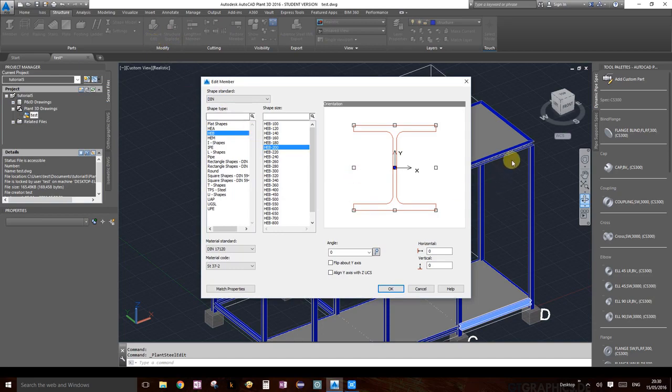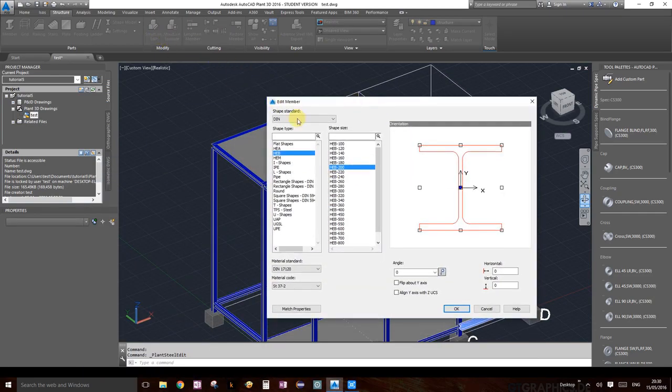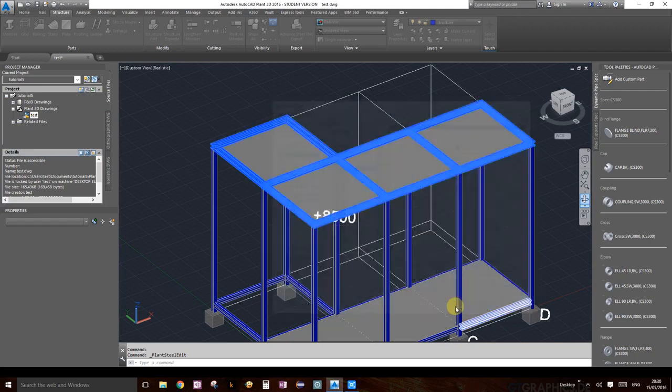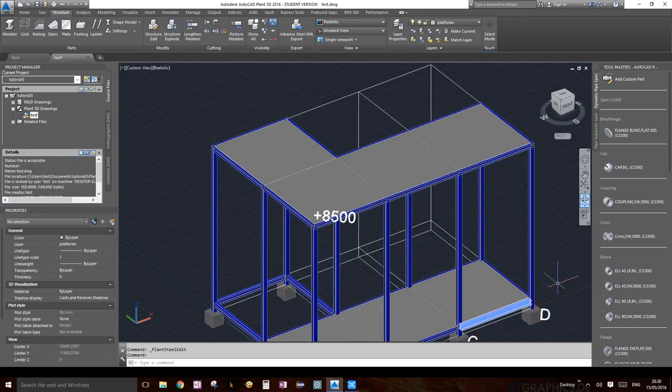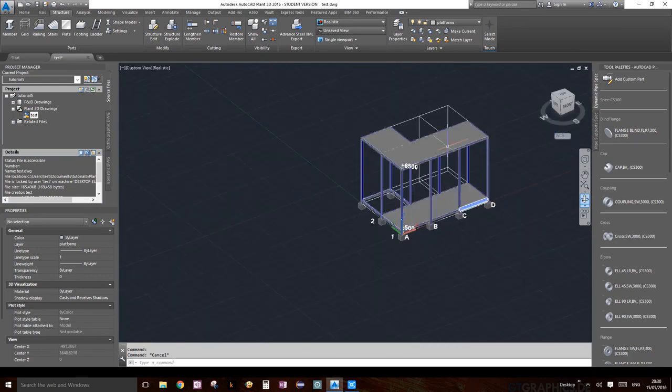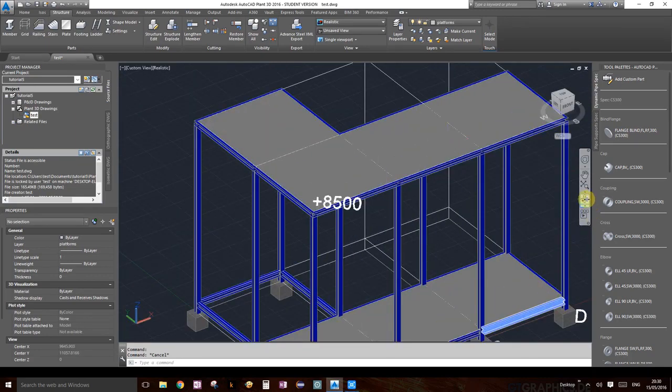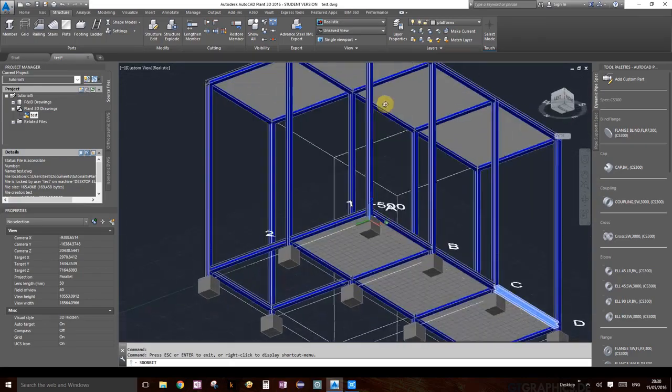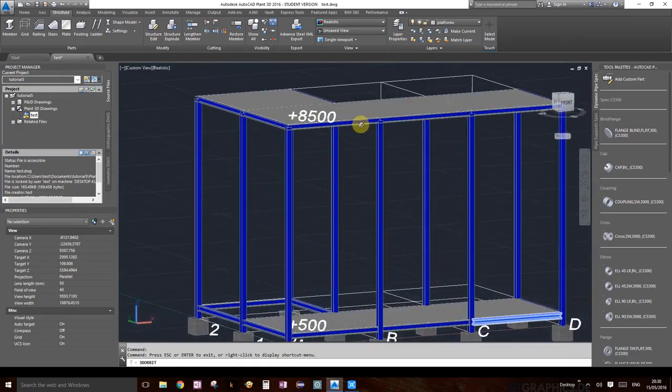So what I've done there is selected all the upper horizontal members and clicked on structure edit, and I'm going to say orientation is top justified, everything else is the same, and bam, it's done. Now our grating has moved to the proper spot. Now you can't see them through it, because obviously in real life you won't be able to see through that.